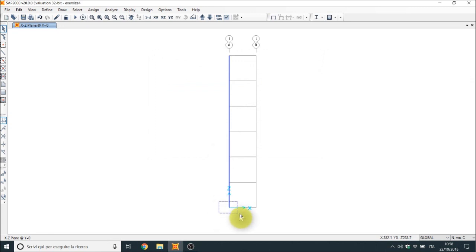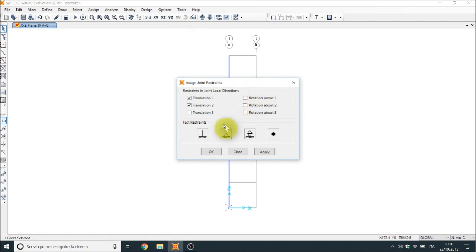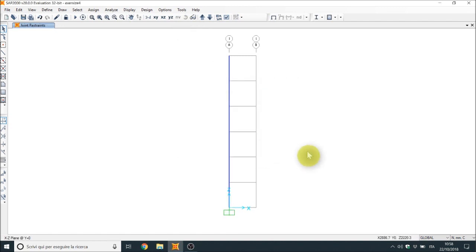So the condition is fixed on only one end. Of course, this analysis is a planar analysis. I consider the buckling and the imperfection in this direction, only in the planar direction. Pay attention that putting a force here is like giving my beam a deformed shape. It is equivalent.